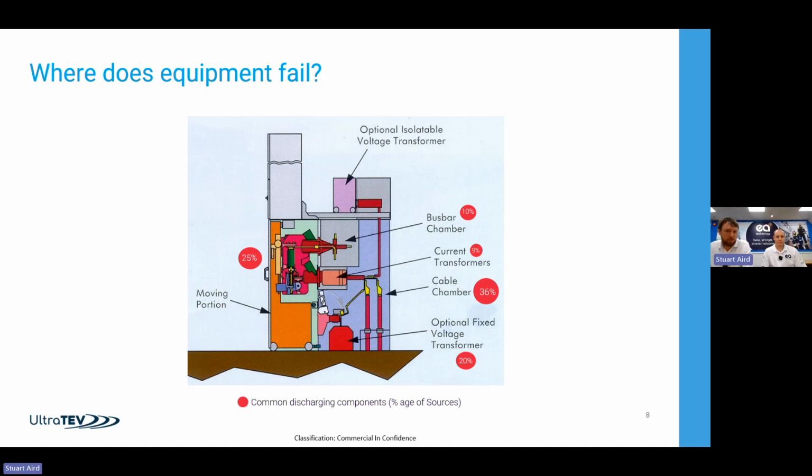You'll see samples that don't just cover the cable terminations or the circuit breakers, but also the fixed portions. So there are some really good case studies, and a safety note probably coming up a bit later on the bus bar area, and the things we've seen there in the last 12-18 months. Wherever it is in the gear, there are examples where it does fail, but statistically these numbers hold true: the most risky parts are where people are involved or things that move.